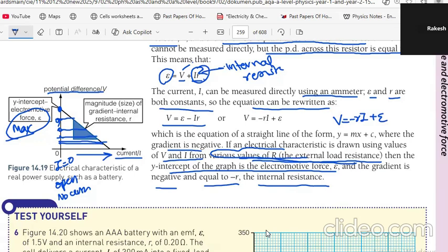Even though the battery has printed on it that it is able to give you 12 volts, when you are using it, you will get 11, 10, 5, 6, depending on what resistance you are using and what current is flowing, because current comes inside this. So you don't get a fixed voltage; that depends on the current flowing. We generally think that we got a 12 volt battery, we'll get 12 volts. No, we won't. What we will get depends on how much current flows, and that depends on what resistance is in the external circuit.